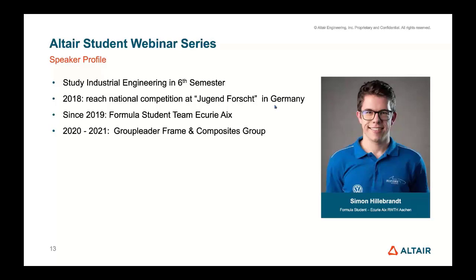All you need to do is just make sure you have the right exterior profile for it. Exactly, so that's for the aerodynamics. The profile shape is important. If you want to then simulate the effect of the aerodynamic forces on the bending of your wing, then you might need to include the foam, but that's then a structural analysis again. So that's basically mapping the aerodynamic results to the structure again. Yeah, exactly. So it all just depends on what results you want.